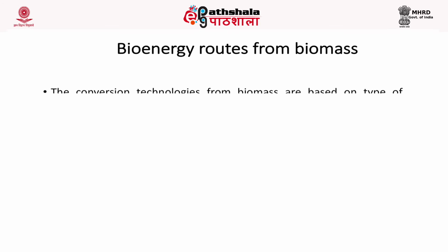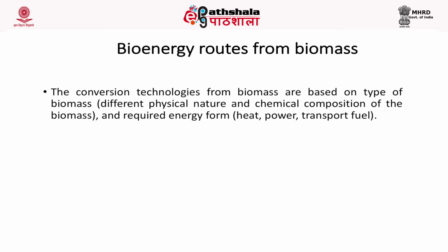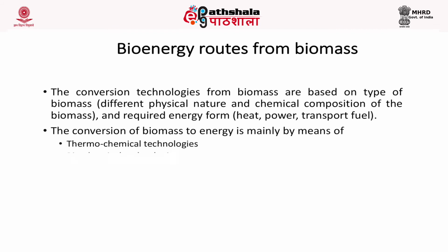The bioenergy routes from the biomass, that is the conversion routes of biomass to energy. These technologies are based on the type of the biomass, that is the different physical nature and chemical composition of the biomass, and the required energy form, for example, heat, power or transport fuel. Based on that, we will use the conversion technology. These conversion technologies are mainly classified into two groups, thermochemical and biochemical, and we can also add one more group into it, that is chemical technologies.